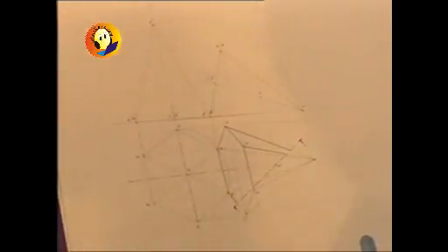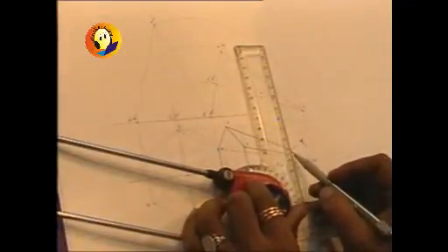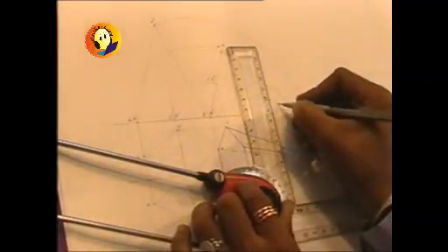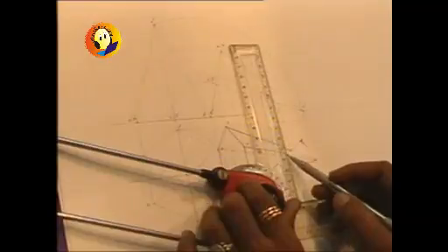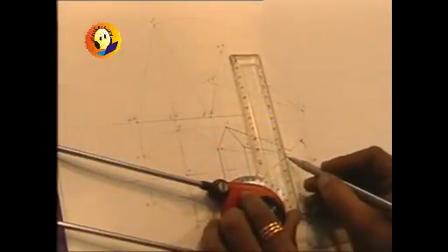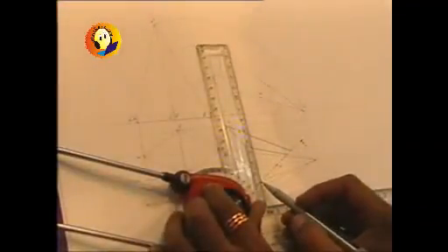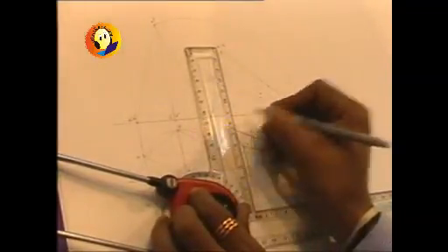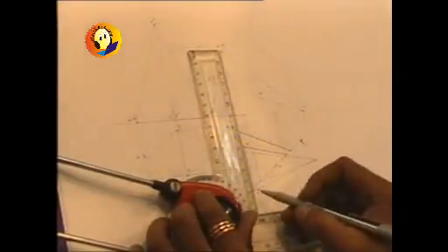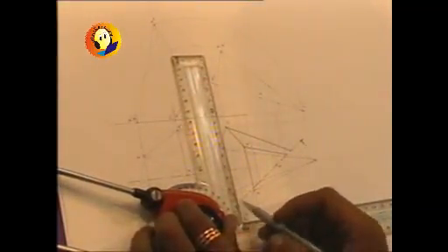Now we are required to complete or mark all these points even in the elevation. To mark all these points in the elevation, we will have to simply draw projectors through each of these points. Like FV is cut at this point, so transfer the point up to FV and mark the point. Then AV is cut at this point, so transfer the point to AV. Then the generator EV is cut at this point, which is the hidden line, so the point on EV can be marked. Then generator DV is cut at this point, so that point also can be transferred. Then side AB is cut, so that point will lie on A dash B dash, and side CD is cut, so it will lie on C dash D dash.